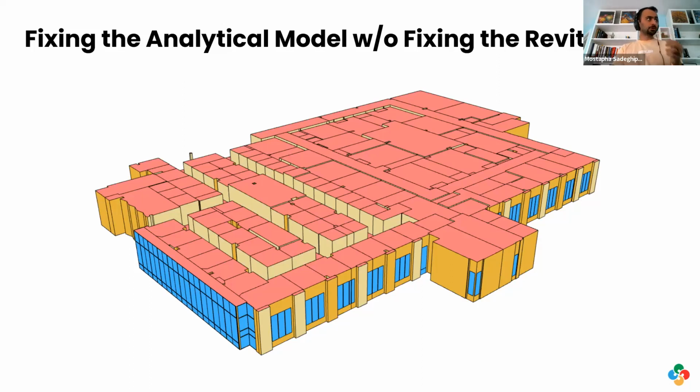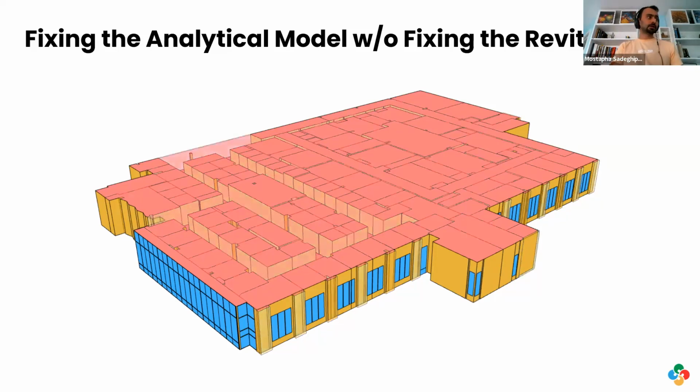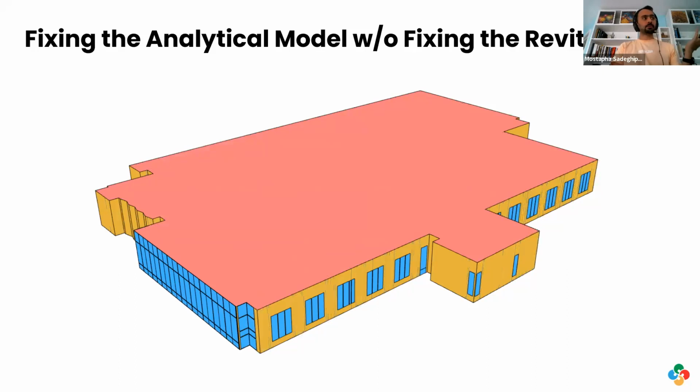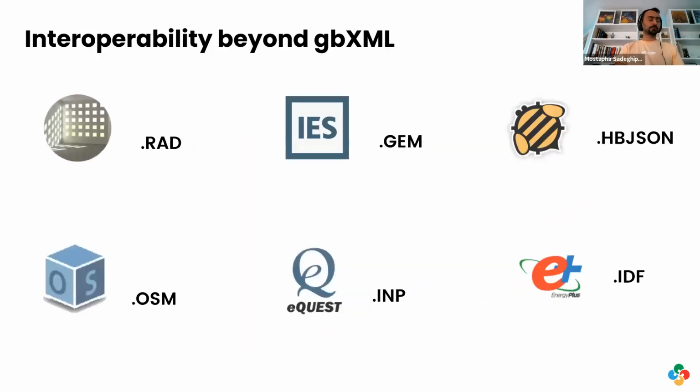So this is a real example, a real hospital building, I think it was 7 different floors. And if you wanted to go and edit every single room, it would have been craziness. And what they really wanted was the whole facade of the building, the envelope. So you can just draw an area and then you get a clean model like this. The Revit plugin takes care of cleaning all of the apertures, merging all of this together, and gives you a single clean room that you can take somewhere else and split into different zones if you want. So the first step is basically resolved here.